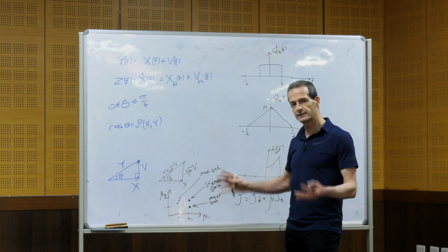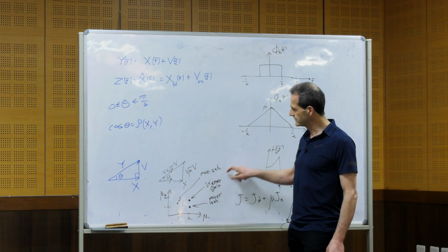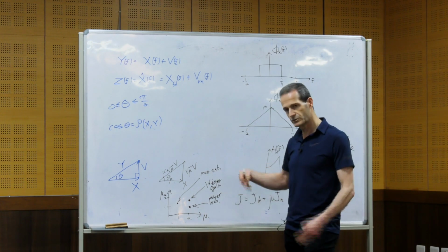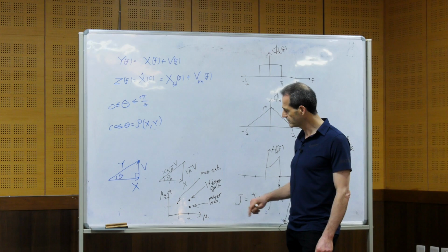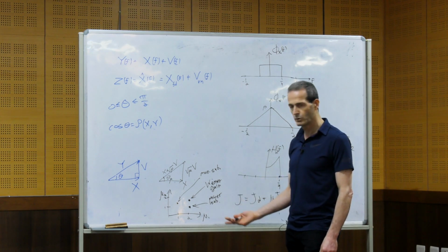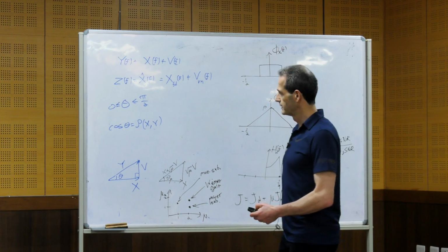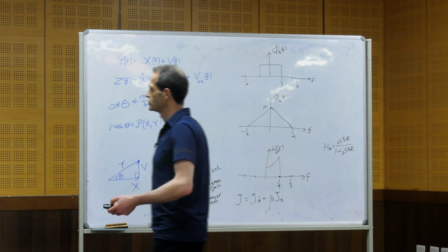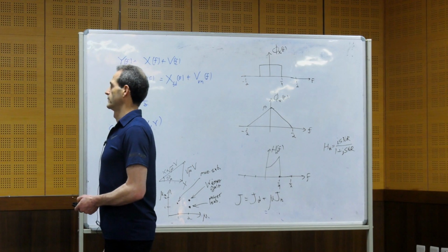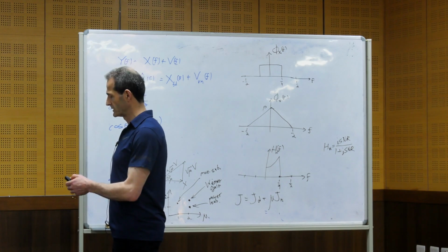But in terms of the distortion also, this distorts the desired signal more because it reduces more noise than the Wiener, and the Wiener reduces more noise than the power subtraction, but also has more distortion. So we can play with that, but you can also choose other parameters, and you can get these relations between them.